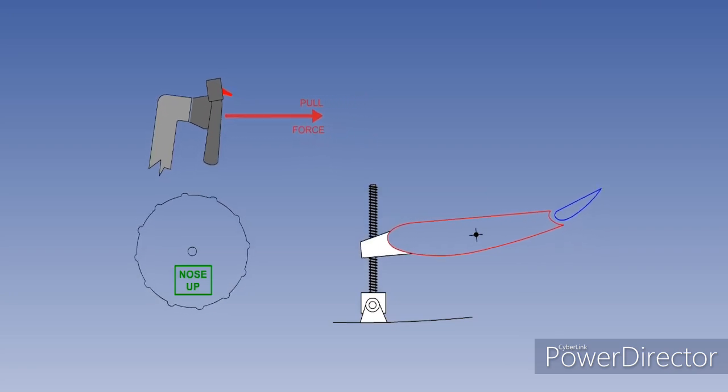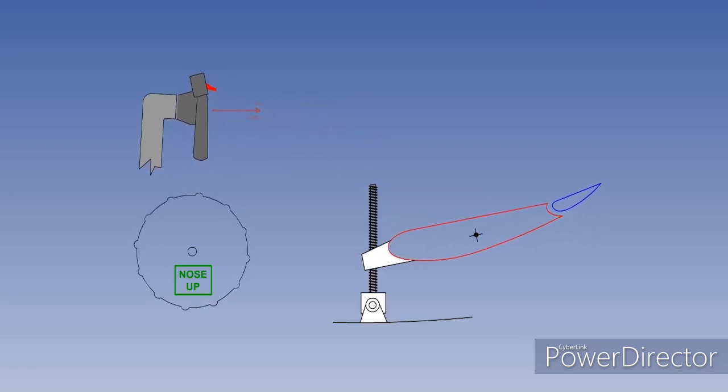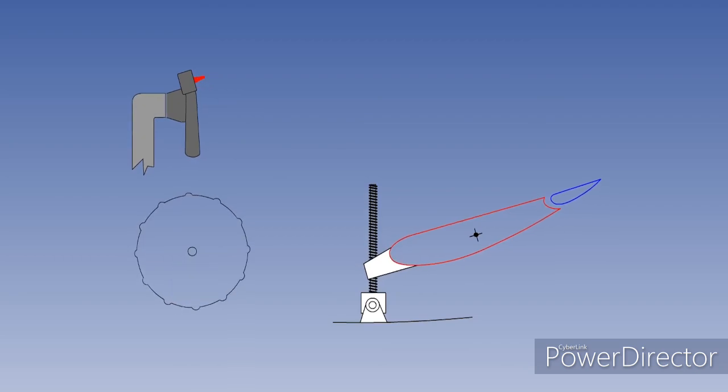To reduce the stick force to 0, the pilot must move the trim switches down. Making this trim input drives the screw jack, which in this case decreases the incidence of the tailplane. Please note that while the tailplane is trimming, the elevator is being returned to neutral. The decreased incidence of the tailplane has replaced the downforce from the elevator. The aircraft is still in equilibrium, but with 0 stick force. The aircraft has been trimmed.